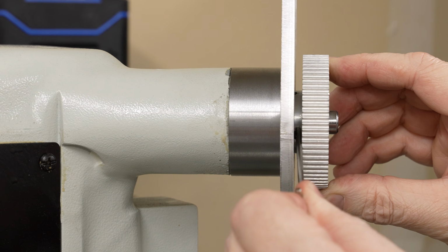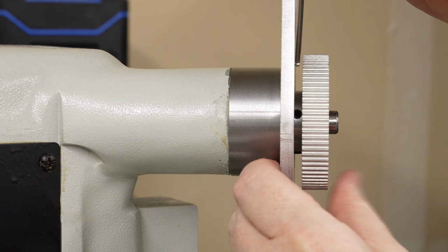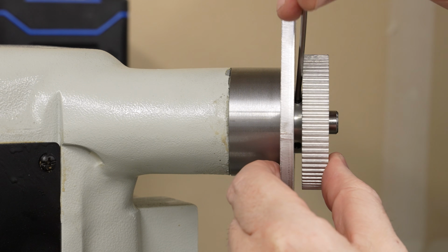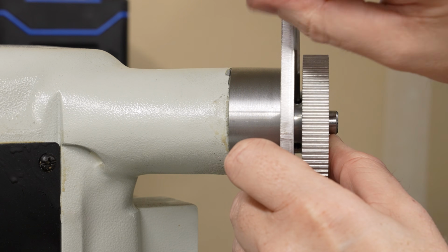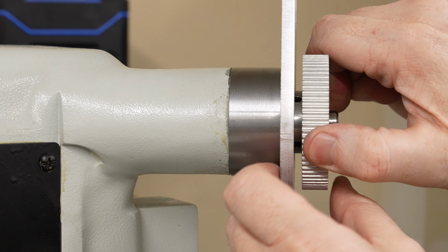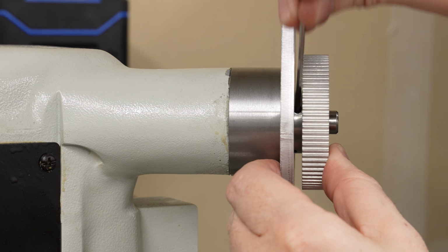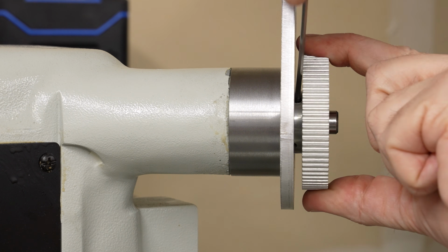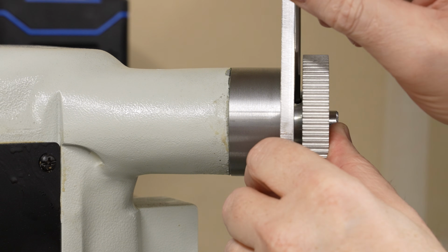I did do a corner-to-corner calculation for the size of the hex wrench for these M5 screws and checked in the CAD model to make sure I could turn the wrench and it was going to clear that plate. And the CAD model said it would just clear the plate, and it looks like it will. We'll get the first one tightened down here a little bit, just so that I can have that bite into the shaft and I can rotate the shaft. Now we'll turn the second one down.